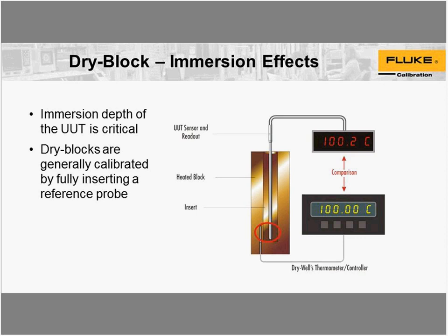So we'll touch on the immersion depth, and it's critical. In my wells, the display sensor is buried down in the bottom of the well. In this example, you can see we're showing a unit being tested in a well, and where the control sensor is versus the UUT sensor.